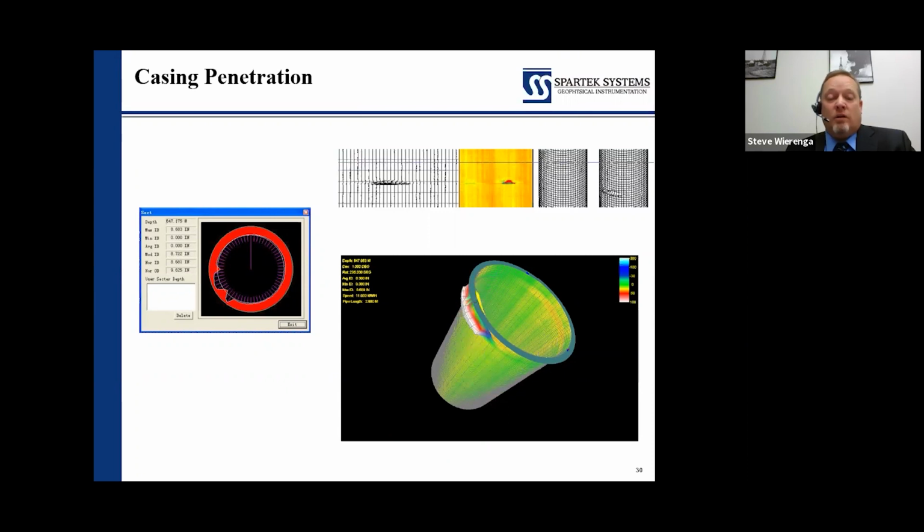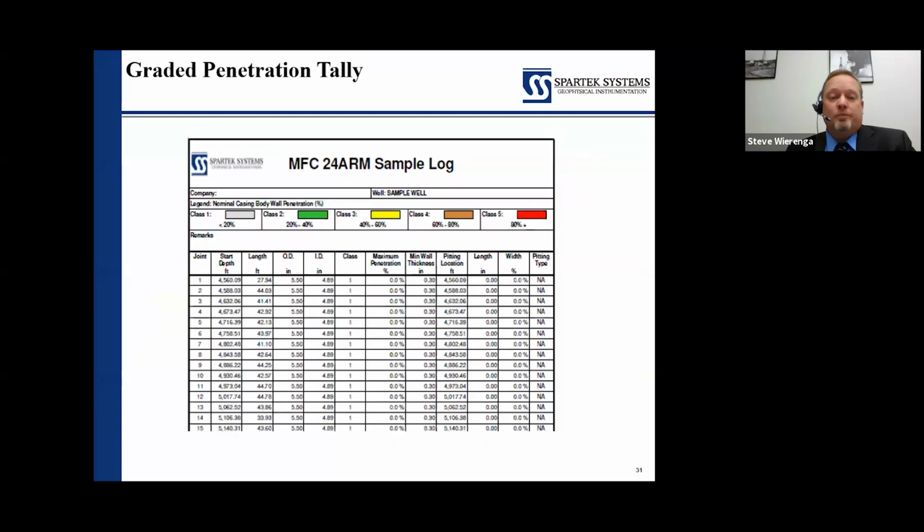Now we can start to take a look at that data and apply it to our forensics and see if we can determine what may have actually caused this issue, or what it is. If it's getting worse, we could time base this. There are also some applications where you can take this data set and turn it into a 3D model and actually print out a copy of it at surface on a 3D plotter or a 3D printing machine, and physically see what that profile looks like and deal with it. I've done a few of those in the past, and it works quite well.